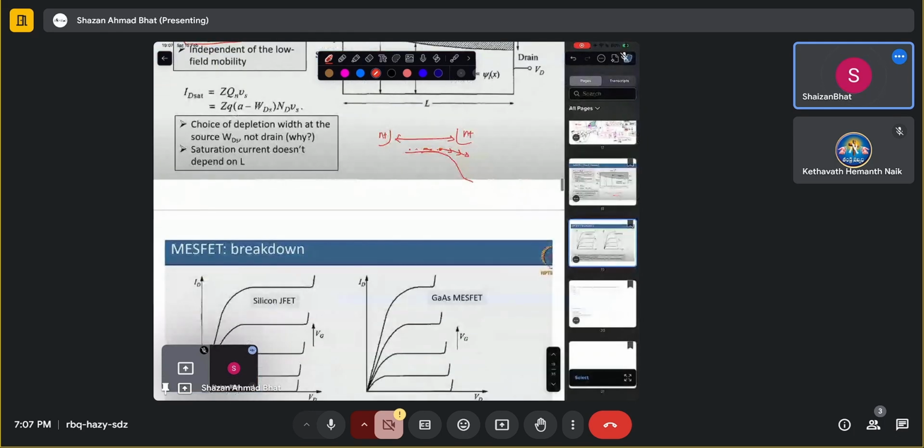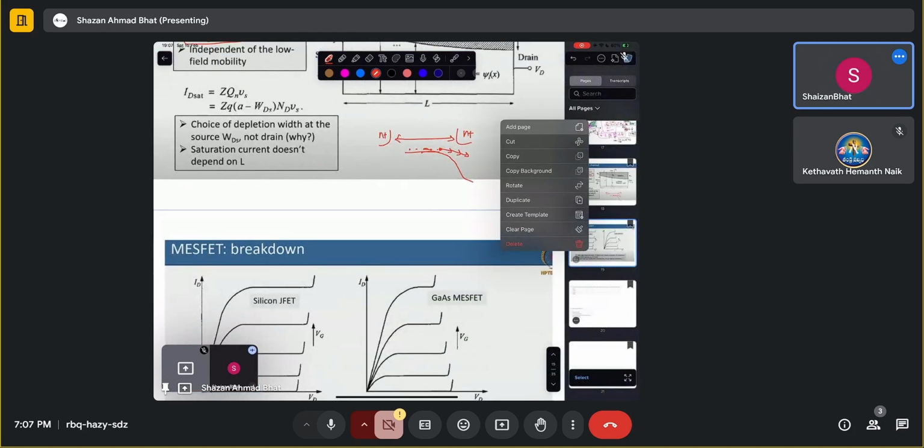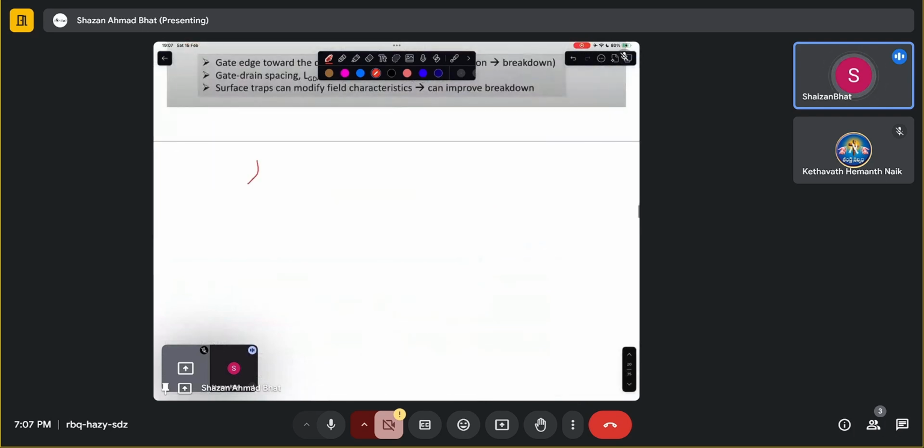It's because, let me show it graphically. If you have a short channel and this is your gate, then if you draw the band diagram of it, you can show it like this. There is a bending in the entire region, because the bending created by the drain extends up to the whole channel. As a result, because of a huge electric field, the electrons move at V_sat throughout the channel.